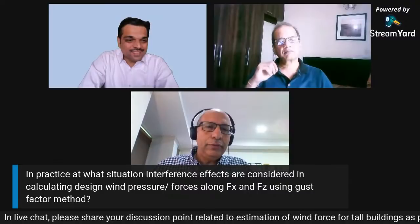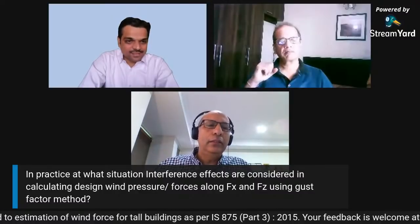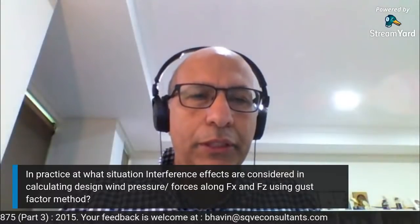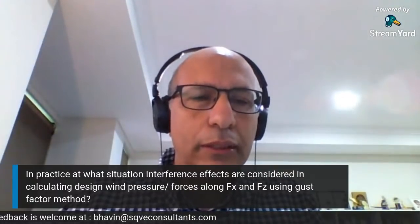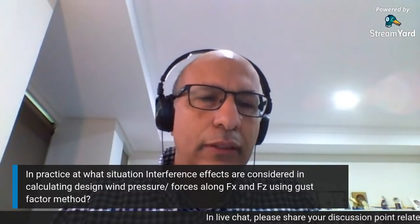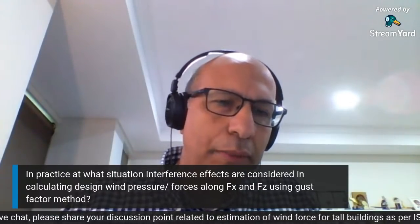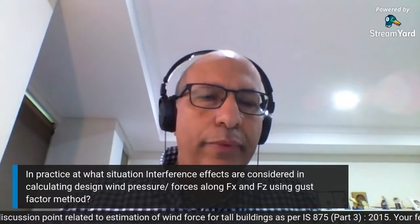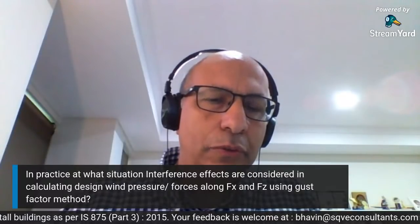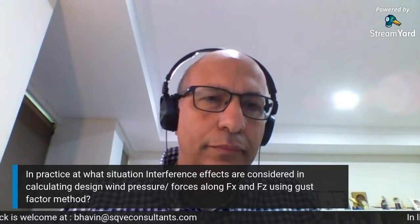So the effect of the interference on pressure is still there, but to a lesser extent, because the pressure is influenced a lot by local turbulence. The wakes shed by the actual study building itself often have a bigger impact than the wakes of other buildings. There are effects, but not as significant as the impact on the overall response of the structure.